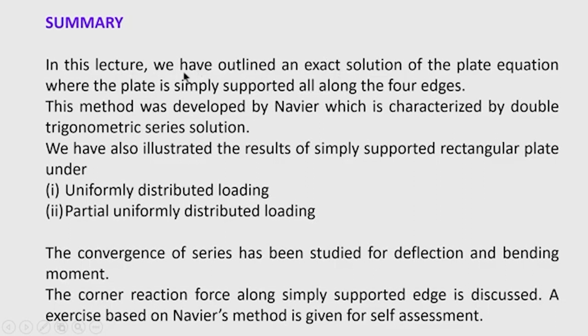So, in this lecture we have outlined this exact solution. Navier's method is used, and it is characterized by a double trigonometrical series, and the method is illustrated by a simply supported rectangular plate with uniformly distributed loading and also partially uniformly distributed loading. The convergence of the series has been tested for deflection and bending moment, and it is concluded that for deflection the convergence is rapid in case of Navier's method.